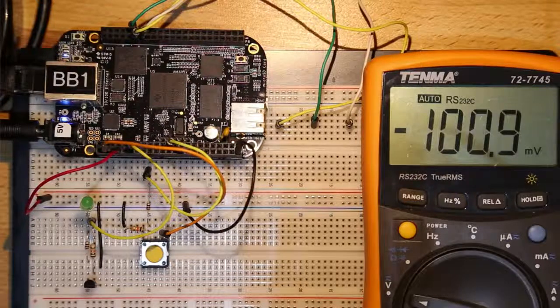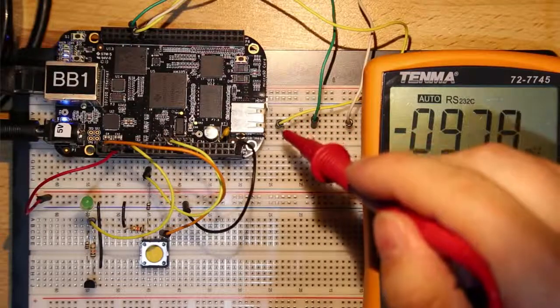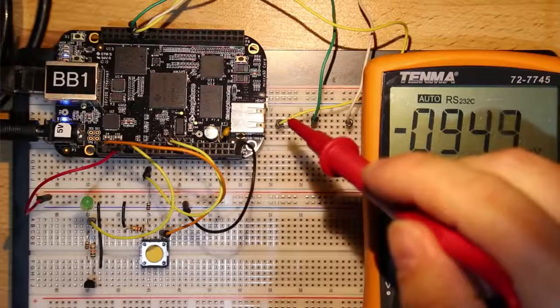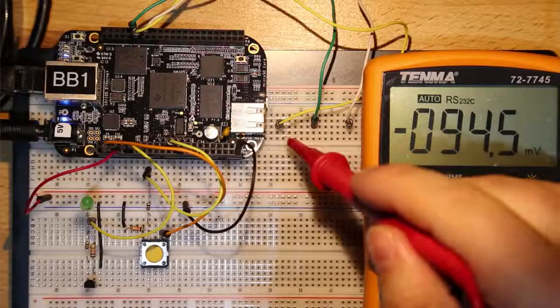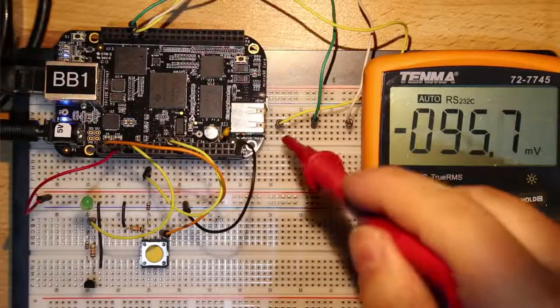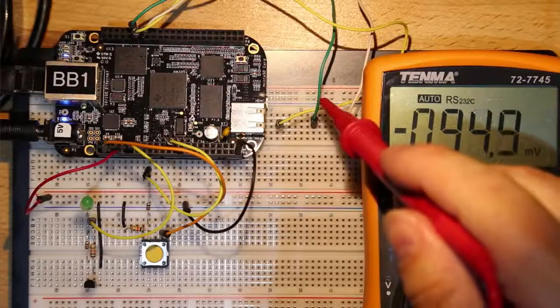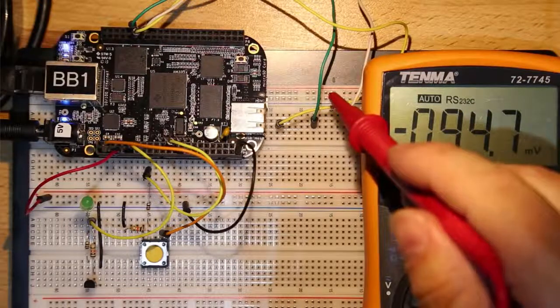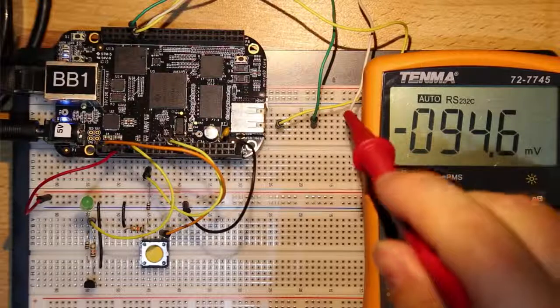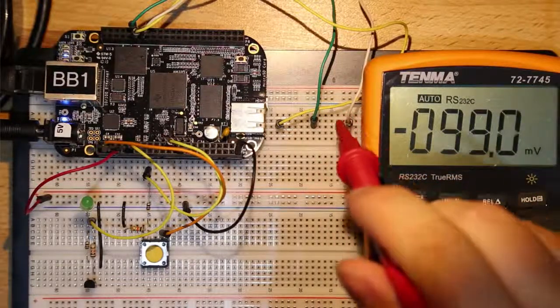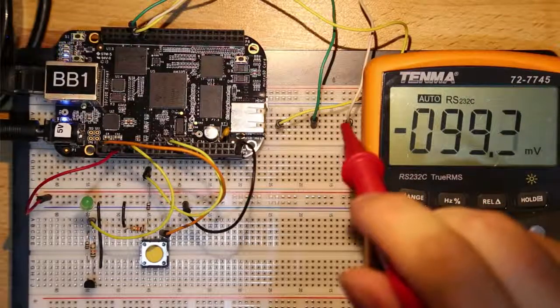So we know from previously that the yellow wire here is connected to P8 pin 11, and this is in mode 7 pull-up configuration, and that is 0x37 hexadecimal. The green wire is in pull-down configuration, and that's because we passed in a value of 0x27 hexadecimal, and the white wire is again in mode 7, but we have disabled internal pull-up and pull-down resistors.